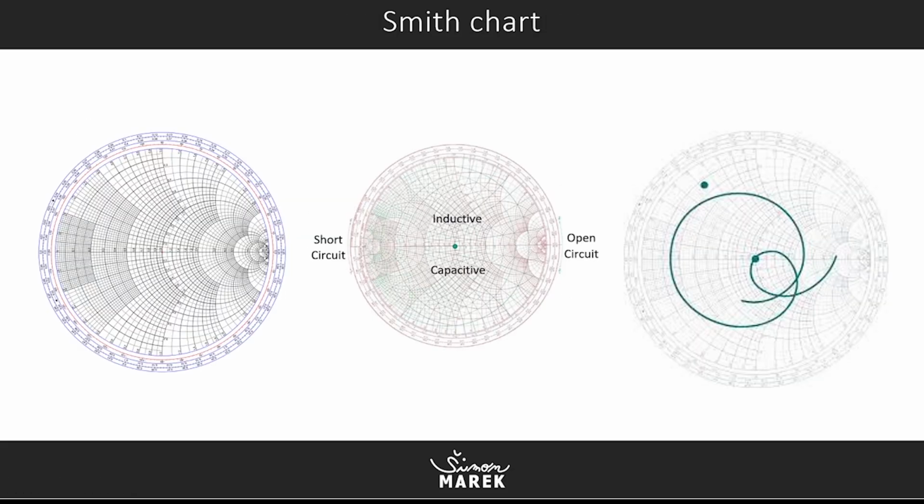There is also Smith chart. It is also important to really understand how the Smith chart works if you want to really analyze your circuit and know what impedance is at the certain frequency.